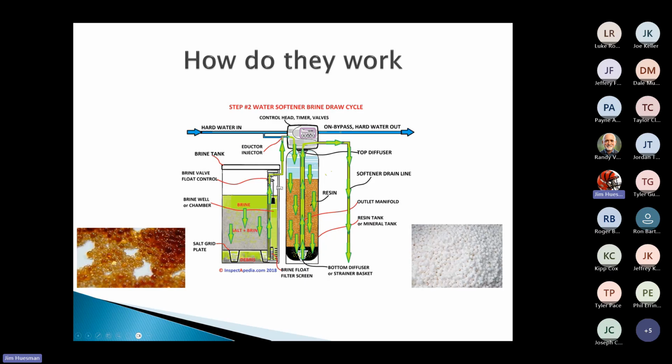Once the water enters that gravel base, it's going to start heading in the up direction, running through our media, okay? That media, you'll hear me using the word ion exchange, and the ion exchange is happening inside of this media base, and I'll explain exactly what's going on. Once the water makes it up through this media, we'll get to the top of the tank, it'll be drawn out, and then sent down to your faucets or whatever we're supplying to that, okay? Now, that's the easy part, all right? So we're able to run water.